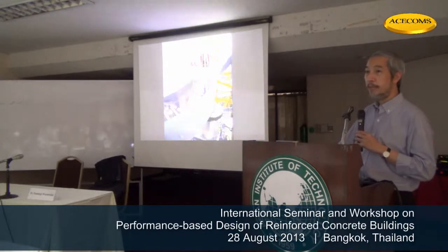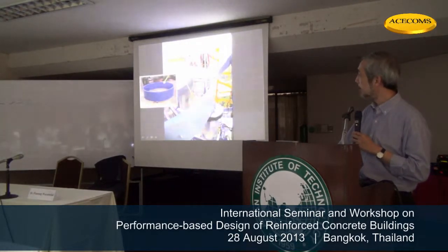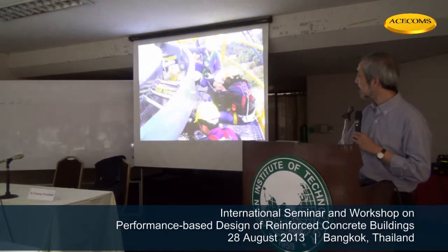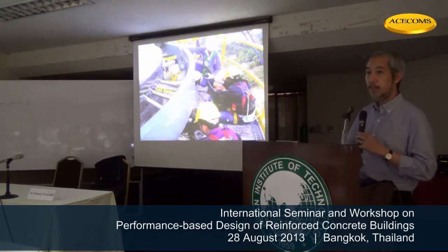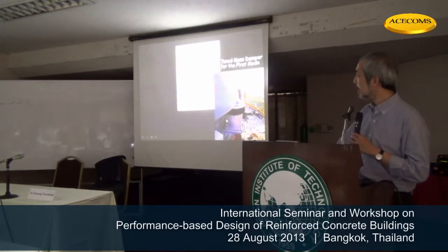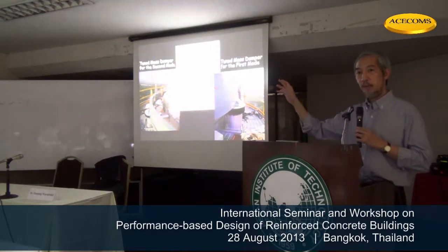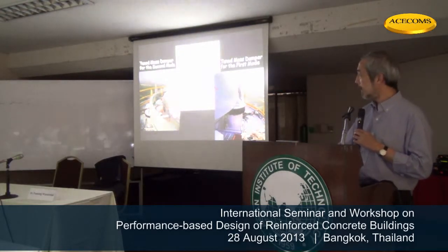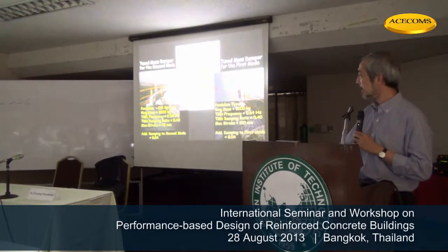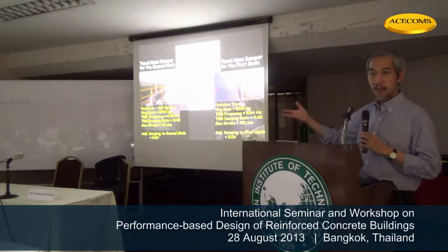That is how we put the damper. This is for the second mode. That's a steel ring, that's a wire rope, the viscous damper. We have a team when we install this damper. And we have two of them, one for mode 2, the other one for mode 1. They are designed with different parameters, which I don't want to go into detail. This is just an overview.